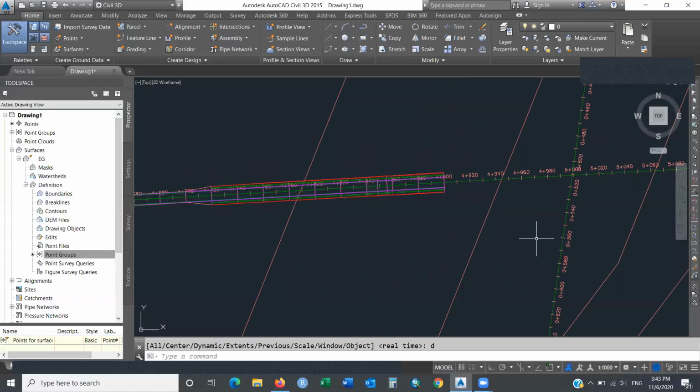We're gonna do the same for the secondary road. Now my secondary road, the intersection is approximately at 510. So I will stop it at 400. In your case, you have to go and see where is that point.